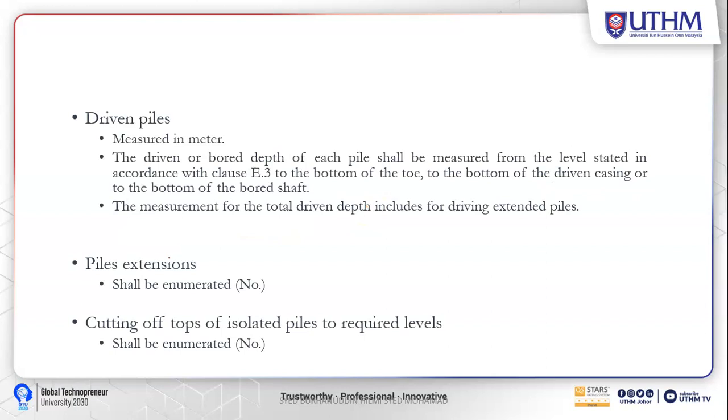So driving piles, we measure in meters. The driving depth of each pile shall be measured from the level stated in accordance with clause E3 to the bottom of the tool, to the bottom of the driving casing, or to the bottom of the bore shaft. It depends.